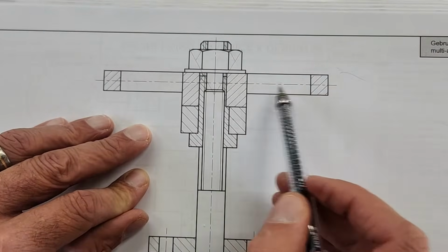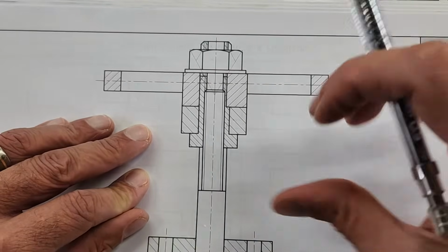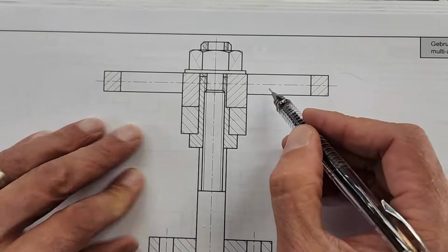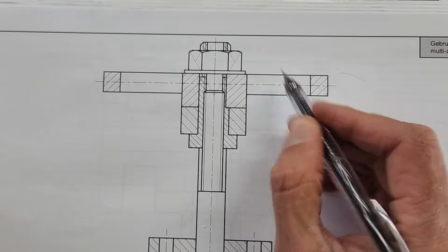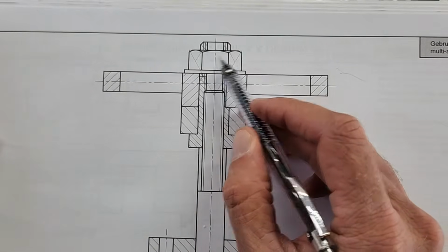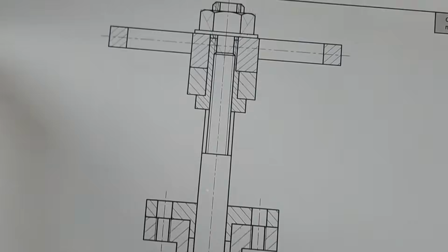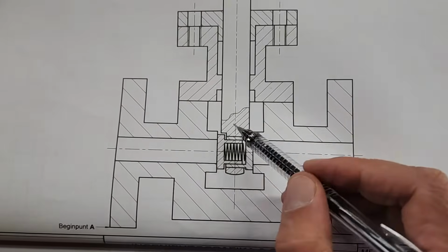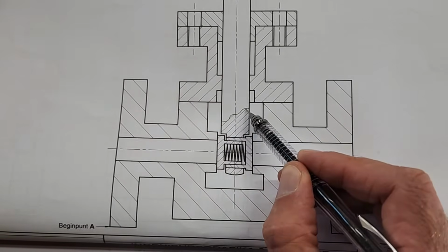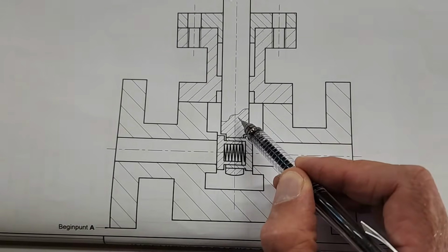All right. On this handle, there is technically also ribs, and so they are not hatched there. The washer and the nut not hatched. Okay. There's a partial section shown here. This you can do by freehand. All right, and that's normally required or specified.